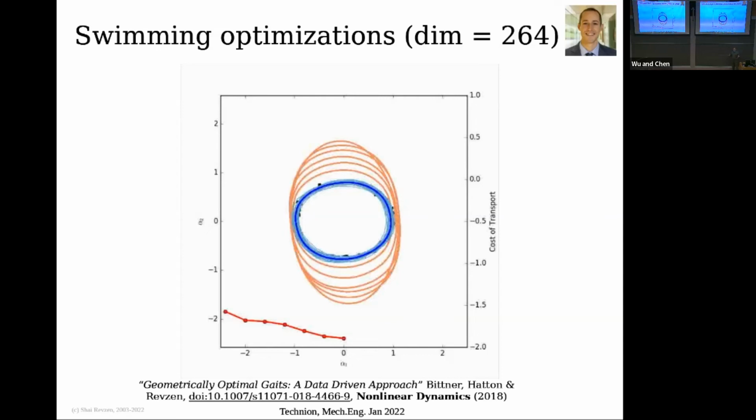Because what we're really doing is we're not trying to build a model of the entire physics. We're trying to build a model of the physics around a gait. So it's a perturbation around a velocity rather than absolute dependence on the velocity. And it turns out that for that sort of perturbative analysis, Coulomb friction and viscous friction aren't that different.